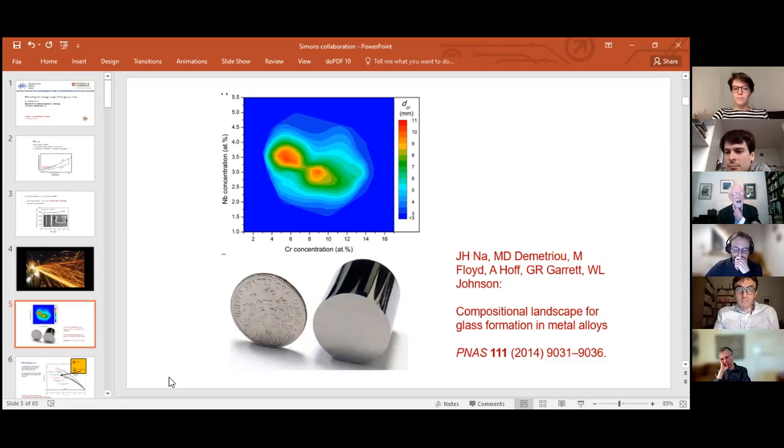So what you would find is you'd have an annular material that would be fully glassy, and then a transient zone of partial crystallinity and probably complete crystallinity in the center if you had the full transition. Which means, of course, that you could be suspicious about many people claiming to have made stuff fully glassy because they may not have looked much beyond the surface.